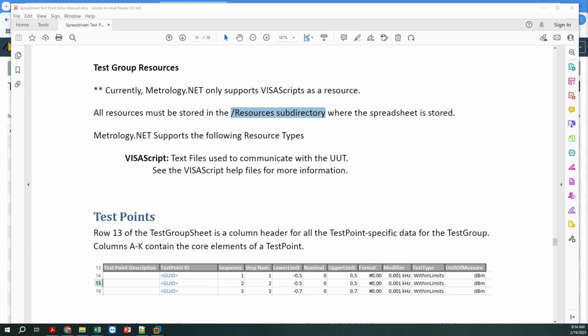Yeah, well, what we need to do, and I believe the 8508 has an update, we'll have to go in and check that, where below a certain frequency, I automatically turn the filter on. I know I did that in one of those two drivers when I was working with the guys at EMI, the UAE's metrology lab, because we ran into that being a problem. We couldn't get the measurement we wanted, and it was because I wasn't setting the filter.